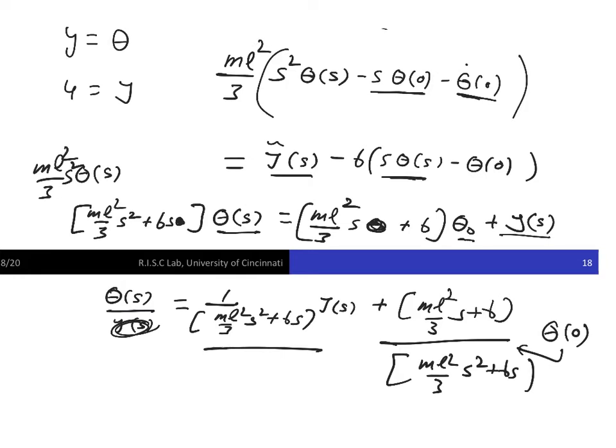And you see that the characteristic equation, the denominator, is the same in both the equations. The only thing that changes is the numerator part. Okay, so if the system is stable, what happens? Let's say your poles are in the left half, means negative. That means things die down because of initial conditions. So this is how you can say that your response is made up of zero initial conditions and non-zero initial conditions. So you basically sum them up.